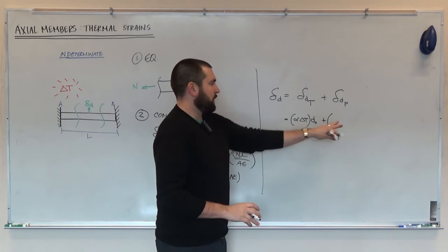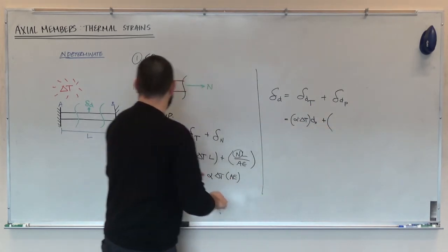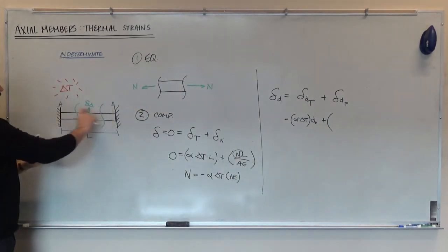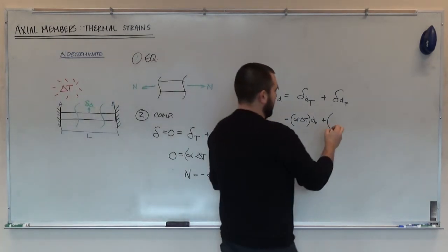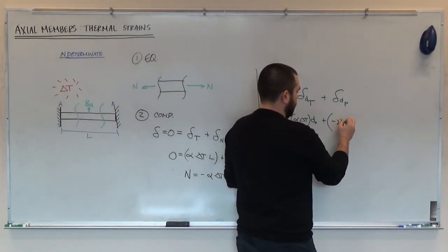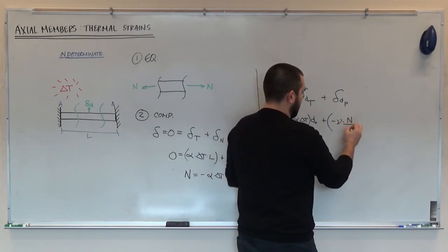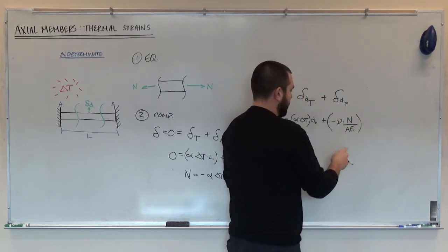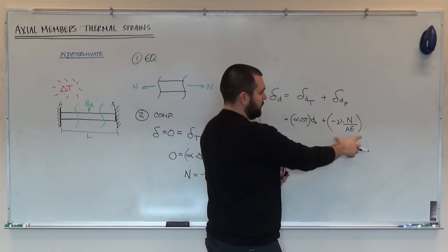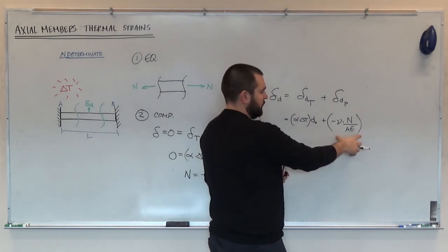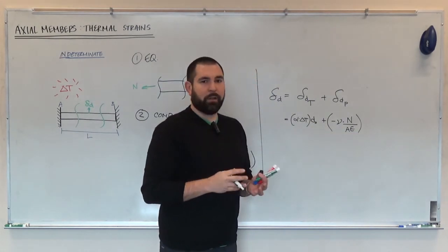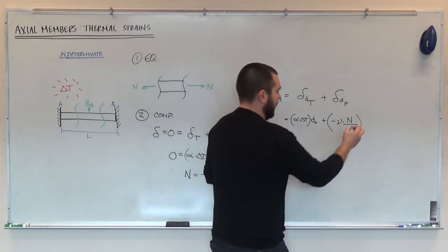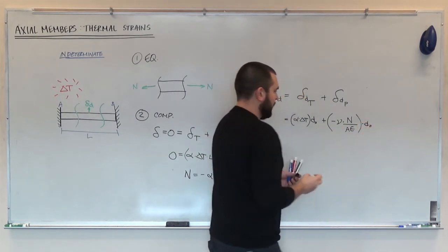and this term here is based off Poisson's ratio. Because we have a column with a constant cross-sectional area, a single prismatic piece, and the internal normal force doesn't change, this ends up being minus Poisson's ratio times N over AE. This term here is the transverse normal strain due to the externally applied loads, due to the internal normal forces. And that gets multiplied by D naught as well.